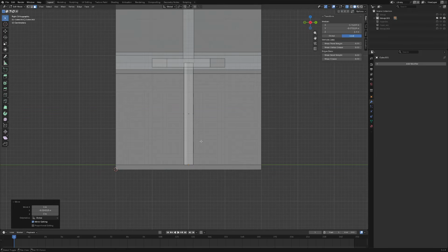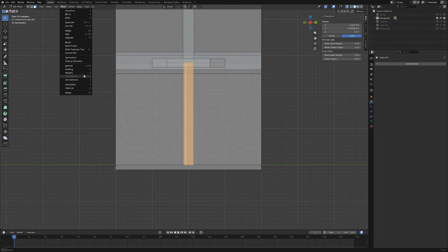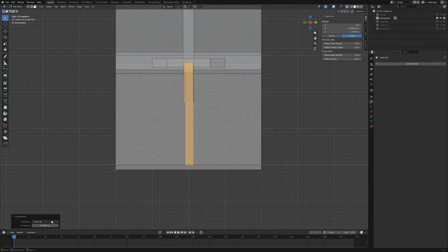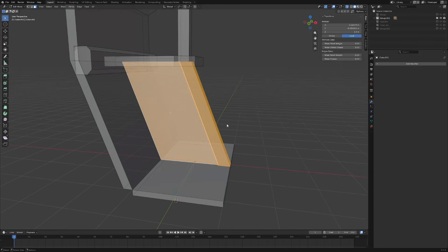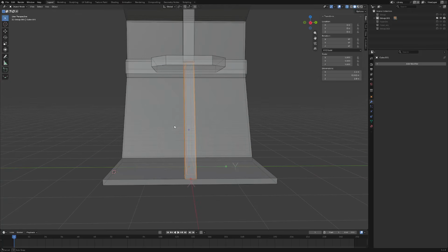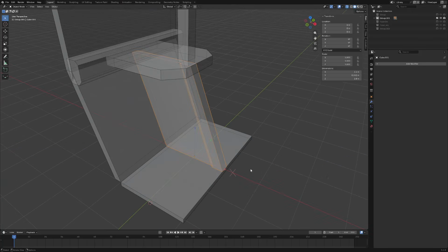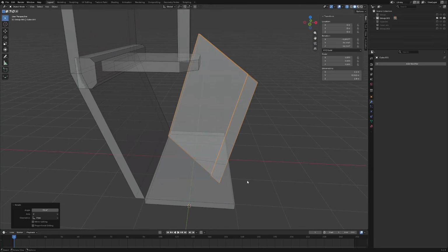So I'm going to move that back a little. So we can press A, mesh, symmetrize, and we'll do, in our case, negative Y to positive Y. You can always tell by the gizmo up here sometimes. Well, not always. This is the world gizmo. If you've rotated your object, it's going to use its local rotation. So in our case, if I hit Control period in object mode, you see Z's up and we're doing Y still. Okay. So local is like this.